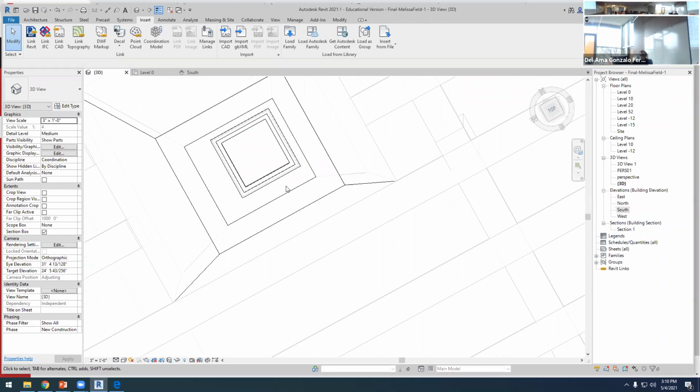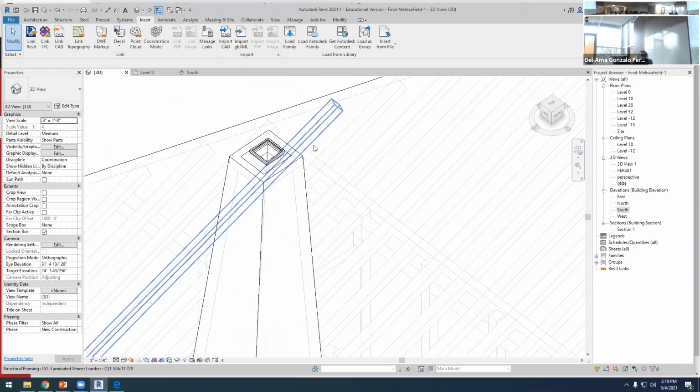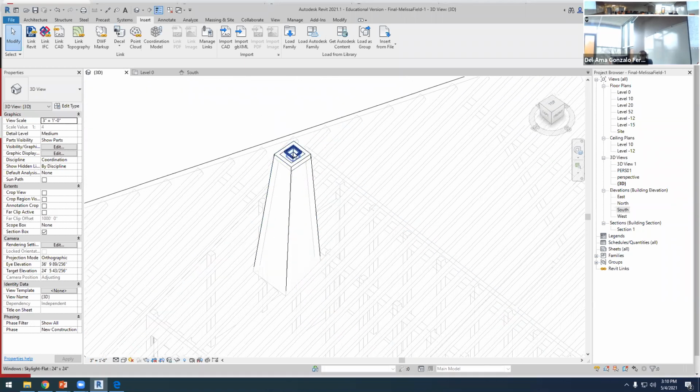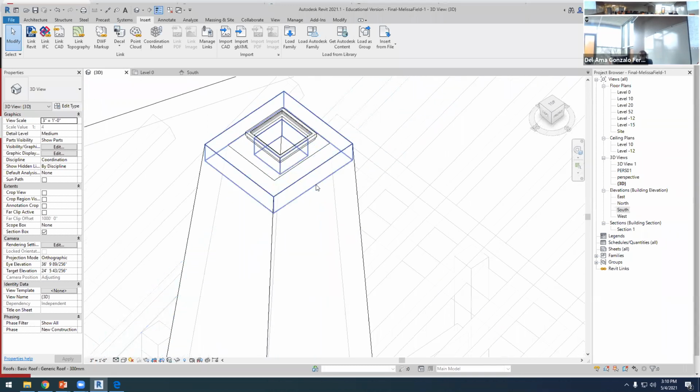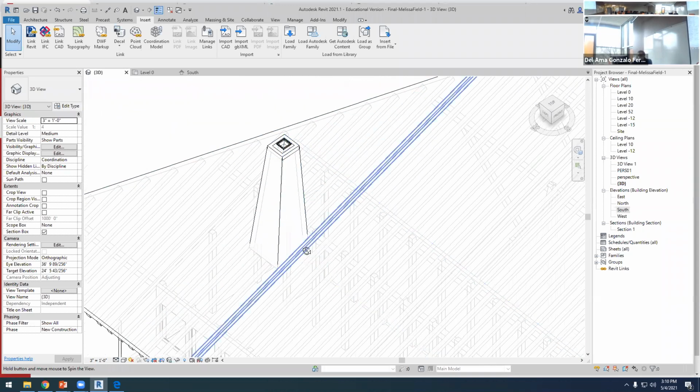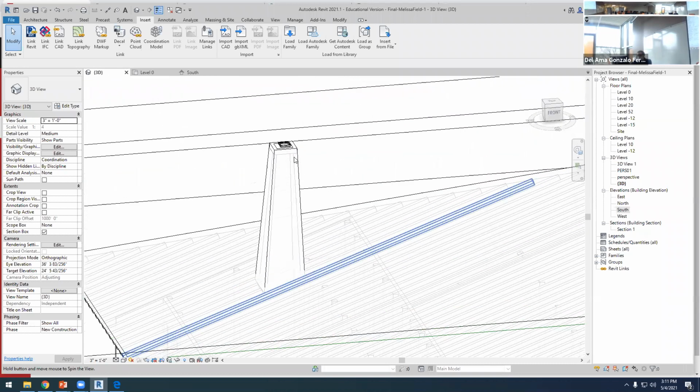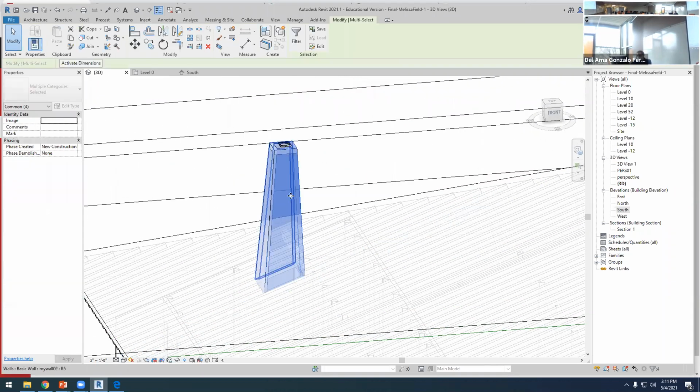The thing is that we need to adjust the size of this skylight to the size of this rectangle. But if we want to open windows, it can be either a wall window or a skylight. We need a host, and in this case, we need a roof for the skylight. So if we're working with the mass, it doesn't work. We have to turn this mass into walls and roofs.